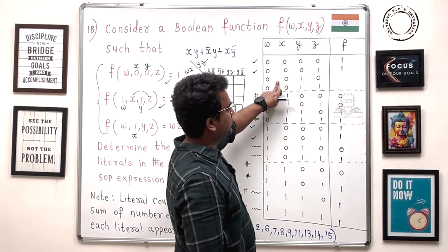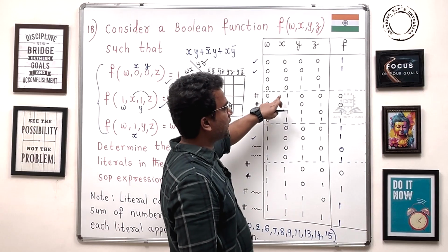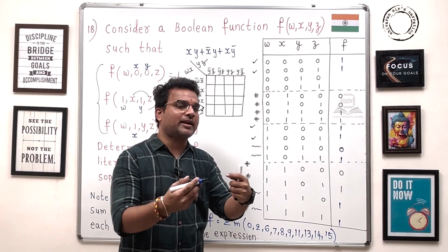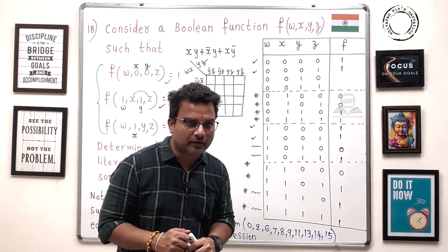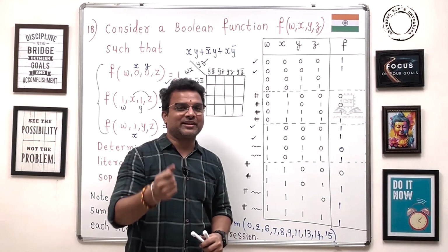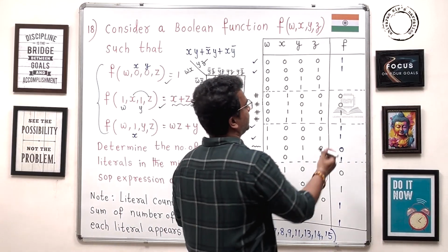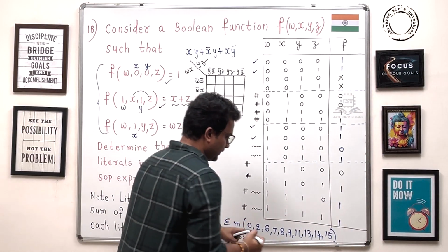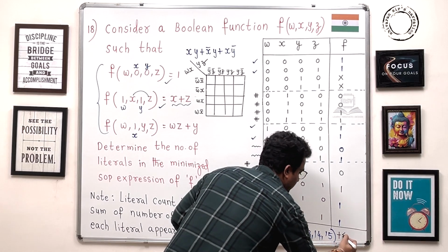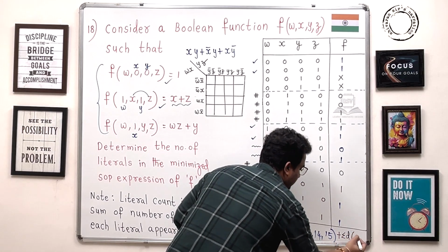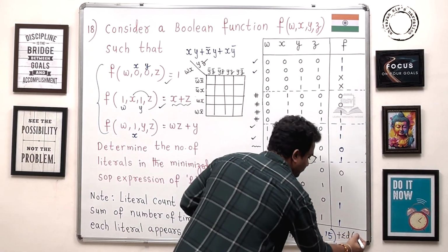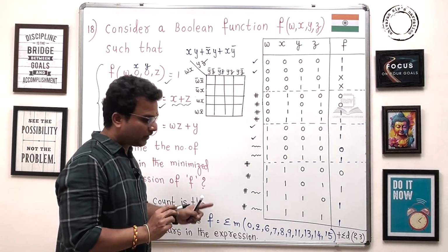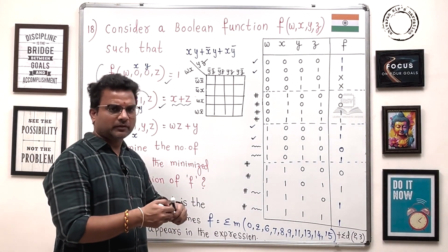That is the 0, 0, 1, 0 combination and the 0, 0, 1, 1 combination, not there. It means it never occurs. If that condition never occurs, it can be treated as don't care. Hence, it can be written in terms of don't care. So here plus sigma d is 2, 3. That's it. We got now the minterms in addition with don't cares.